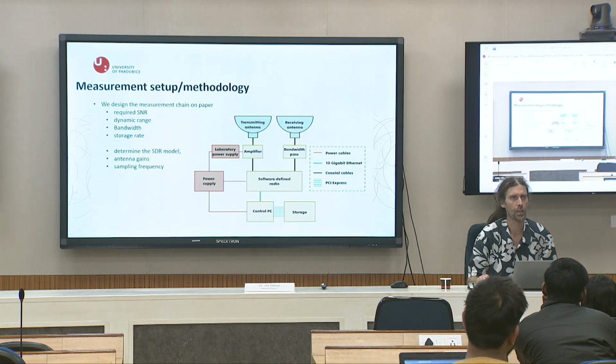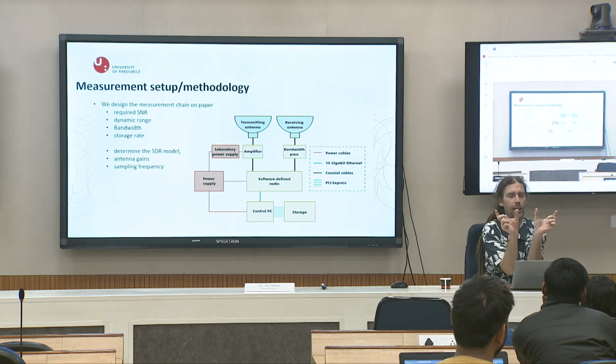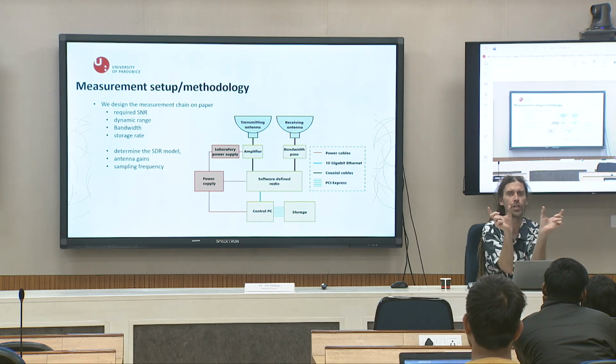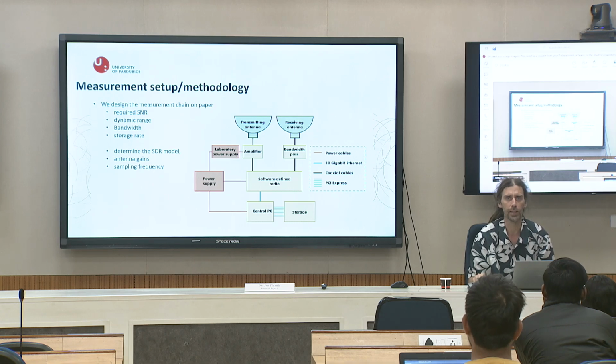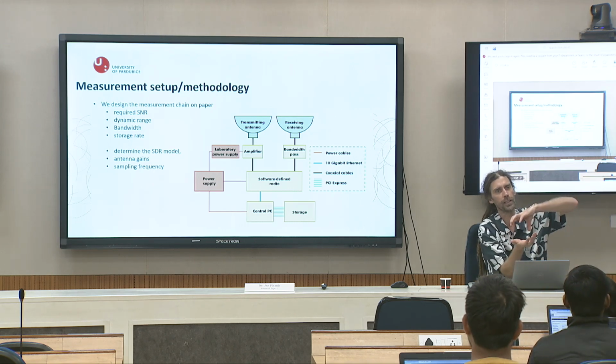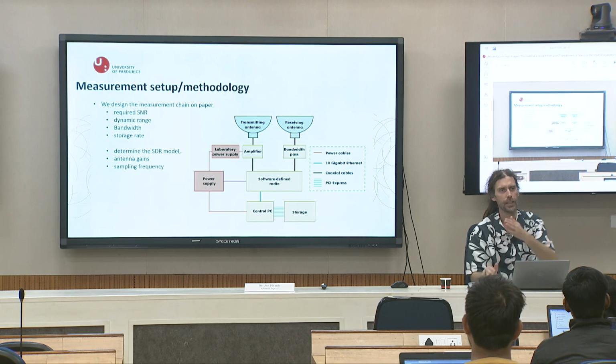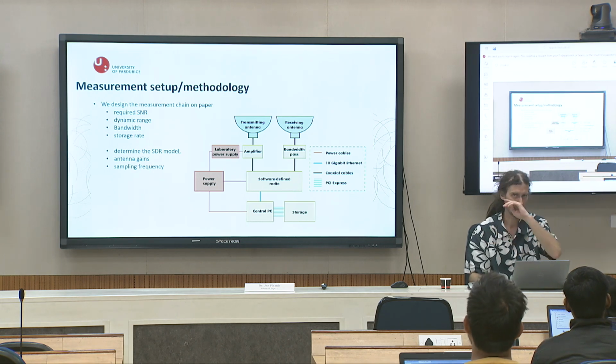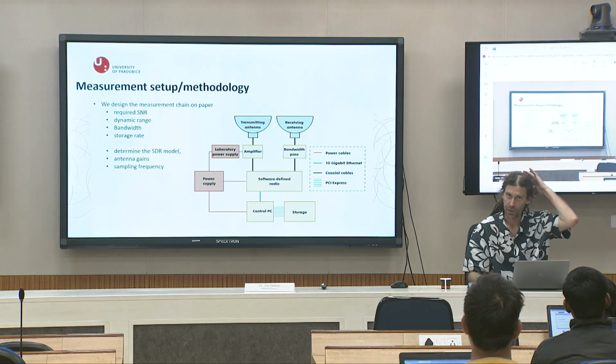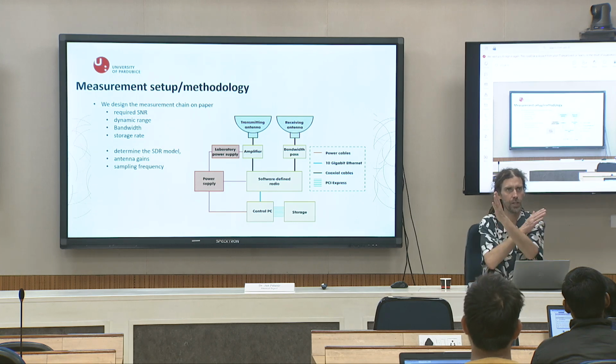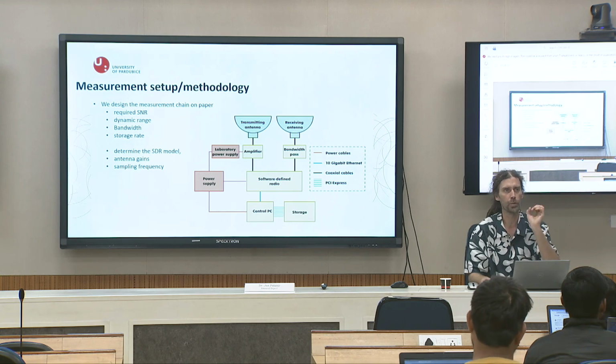And why almost? Because the transmitting and receiving antennas are about 1 meter from each other. And why do we use this? Because we don't need a circulator, we don't need switching between transmission and receiving, we just make a continuous measurement.